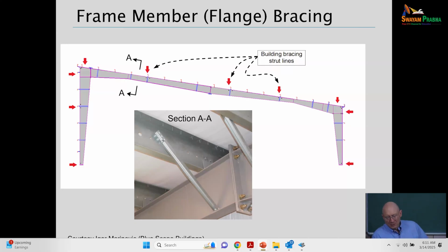If we zero in on a location like section AA, and we see clip attachments of the top flange to looks like a Z-type cross-section for the purlin there. And then flange diagonal coming from the purlin down. Generally, we want to bring that diagonal in and attach it as close as we can to the inside flange, to brace the inside flange.